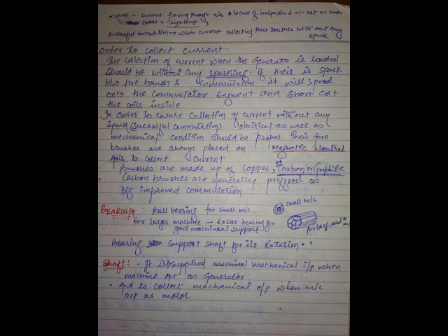I am representing this diagram in an easy way, in a horizontal way. Just imagine. North pole, north pole. This is stator, south pole, stator part. And you know these are all the armature slots. Just represent like this. If the first slot comes under the north pole, automatically the seventh slot comes under the south pole. That's what I have represented. So now you want to design this coil.